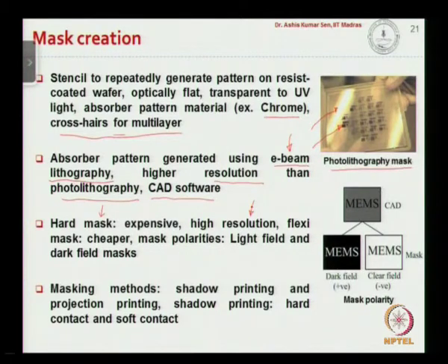Okay. And we use e-beam lithography to write this high resolution mask. Flexi masks on the other hand are cheaper. They can be simply printed on a transparency sheet, and the resolution is typically poorer as compared to the hard mask.